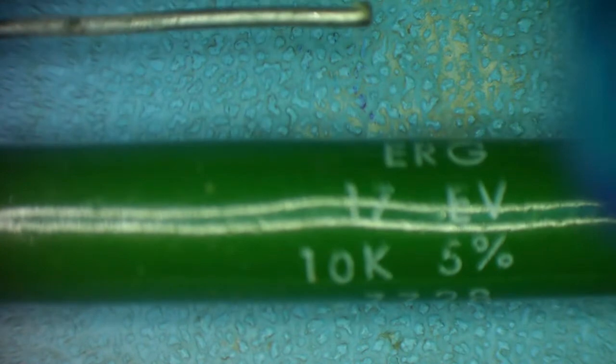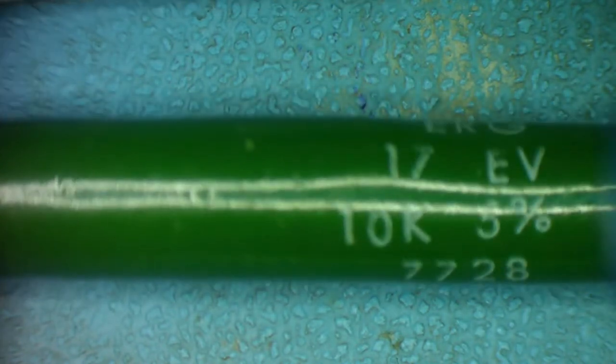What else do we have? Here's a bigger one. Too big to get under the microscope, yeah. I'm pretty sure that's another wirewound. Look, this is marked here 10k, 10 kilo ohms, 5% the tolerance, yeah. And the rest would be manufacturers, and it was probably made on the 8th of February 1977. That's probably what that little code means. But that's a 10k wirewound resistor.